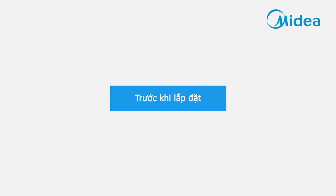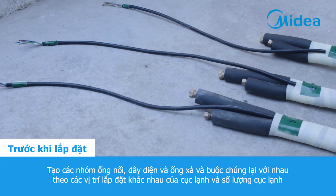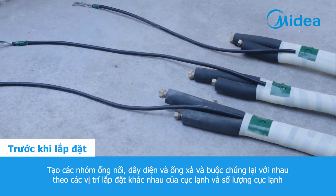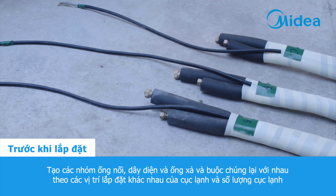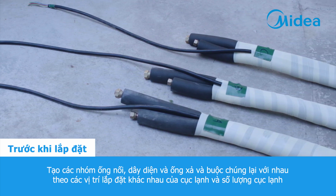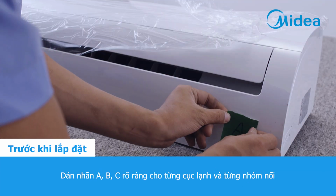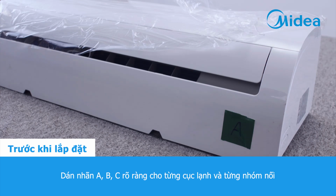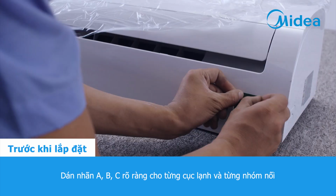Before installation, make several groups of connection pipes, wires, and drain pipes and bond them together according to different installation positions of indoor units and quantity of indoor units. Make clear signs of A, B, C on each indoor unit and each connection assembly.